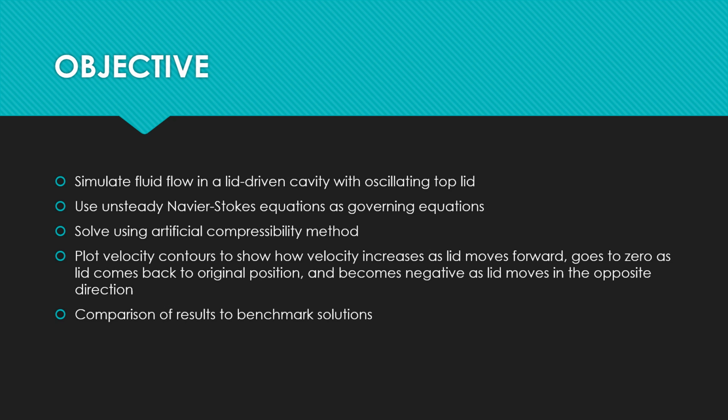This problem is solved with artificial compressibility method on the unsteady Navier-Stokes equations. We want to visualize how the velocity contours change as the top lid moves to and fro. Apart from this, we would also be comparing results to benchmark solutions.